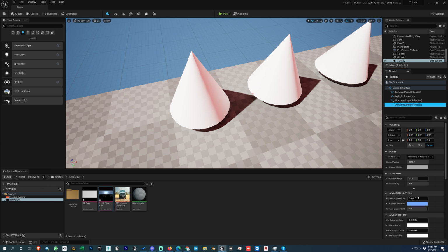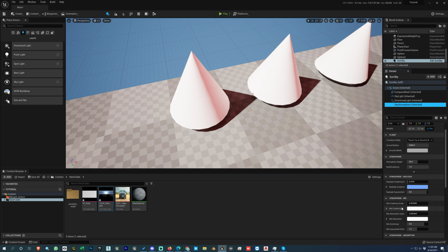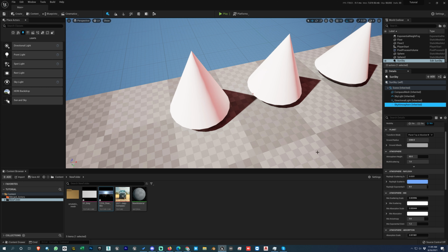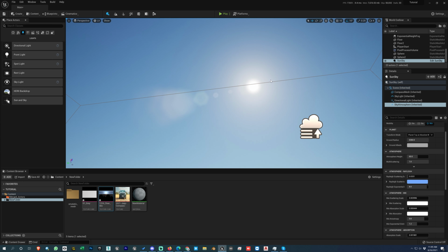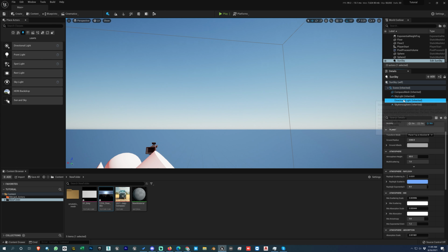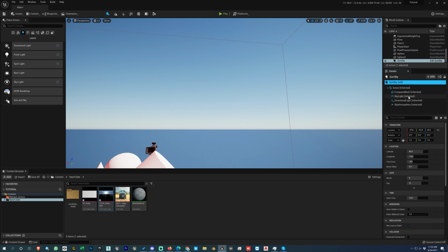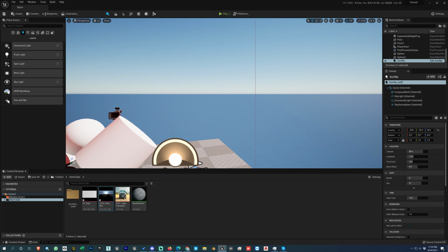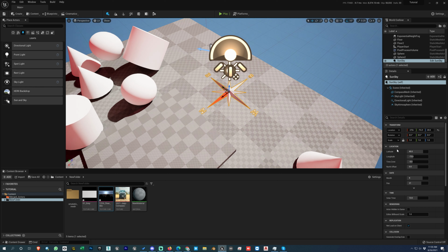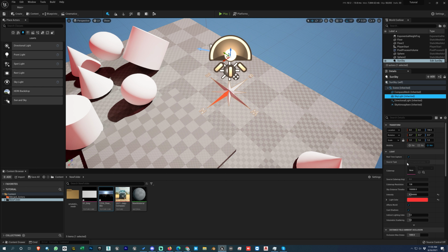And this is just the sky atmosphere. This should be used. It doesn't do a lot in the scene, but it helps to get a good environment. You see here, the sun is available and all those things. Also in the directional light, when you scroll down in the atmosphere and cloud, make sure atmospheric sunlight is on, and anyway when you are using sun and sky, it will be automatically on. The main thing to note here is that you have to click on sun and sky, and then you can change the latitude, longitude, time zone, north, and all those things. You can go into skylight and you can have all these settings.